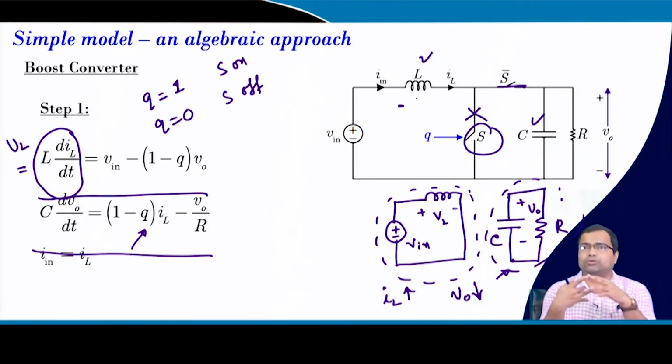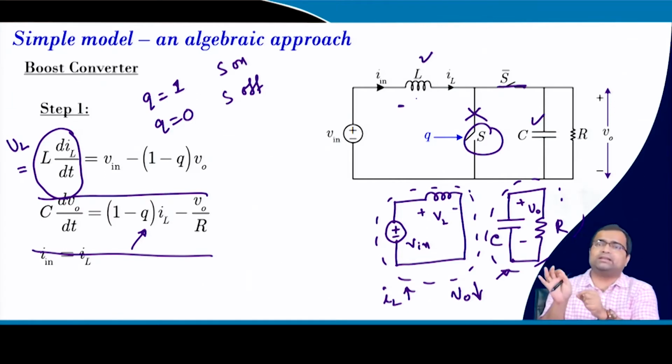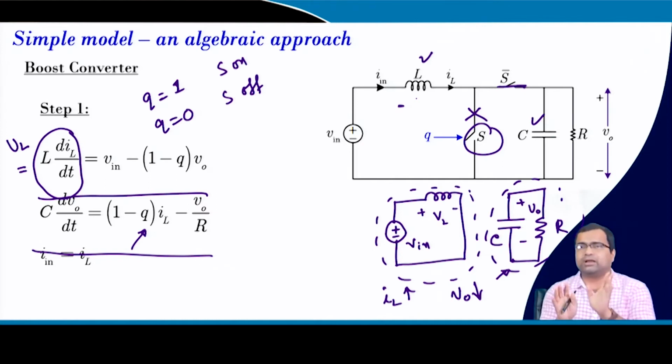In that case we need to put a capacitor, because the solar panel should not be exposed to the discontinuous current. But in case of battery charging or LED driving, where on the load side we need a continuous current, we generally apply a buck derived topology, where the inductor is on the output side. Okay.